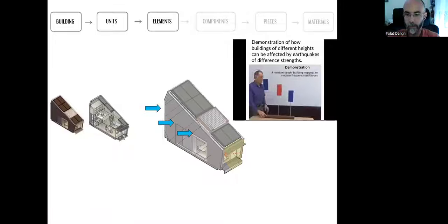If I move it more briskly, I can dial in the rate of horizontal oscillation so that I move the center building, the intermediate height building, and the short and the tall ones are barely moving. To get the short building to oscillate, you need to move the base very briskly back and forth.